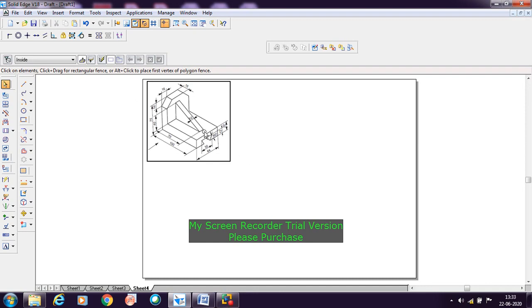Now in this case, when you take the side view in this direction, this is called the right side view. You'll be looking from the right direction, from the right hand side. So this is the right side view that we need to place on the LPP, that is the left profile plane. The profile plane, the side view plane, which is placed towards the left of the front view and top view, is called LPP, left profile plane.